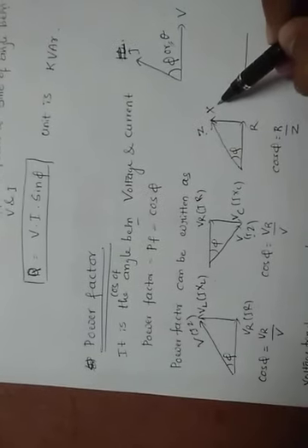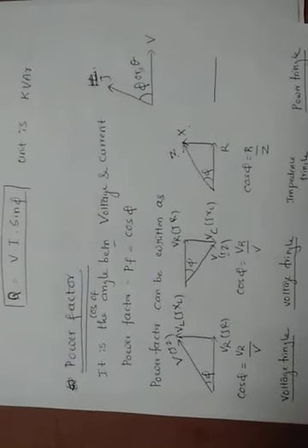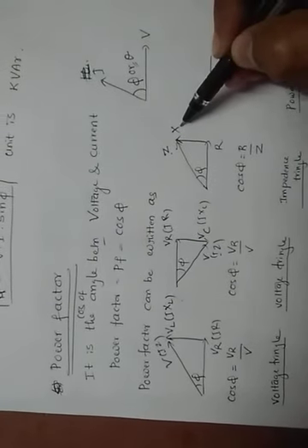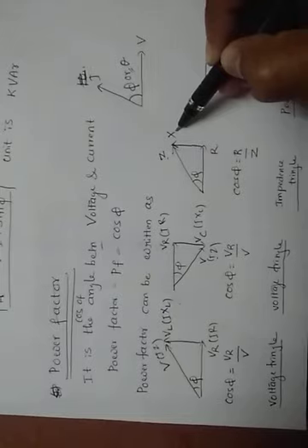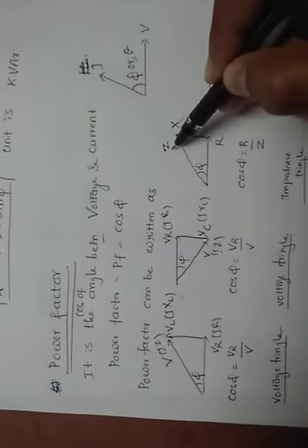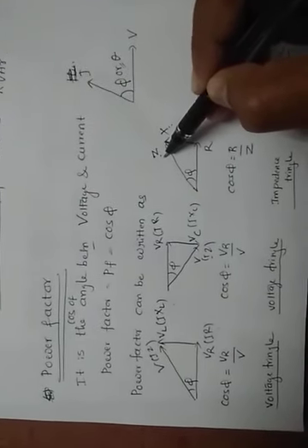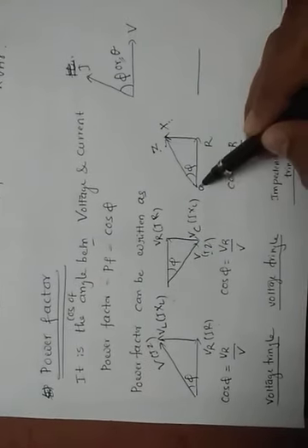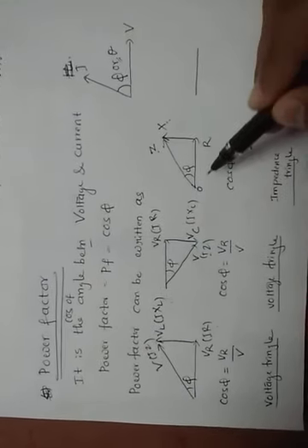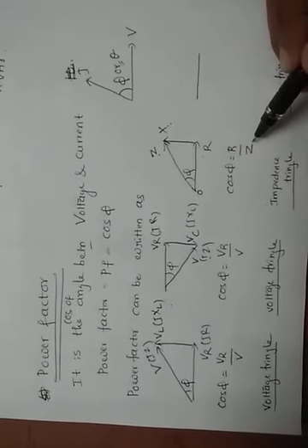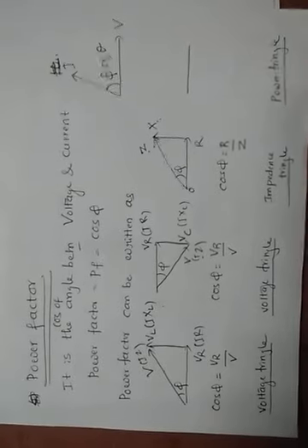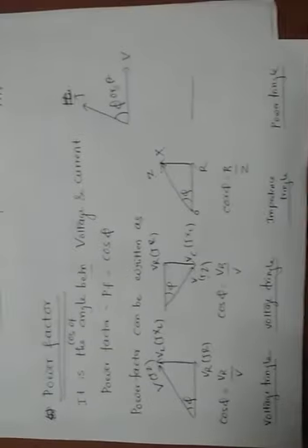In general we are making X, maybe XL or XC. So generally it is R, and XL or XC together will give the Z. So it is called the impedance triangle. Even in this case, if you plot cos phi, it is nothing but adjacent by hypotenuse, R by Z. Like this we can get the power factor formula.